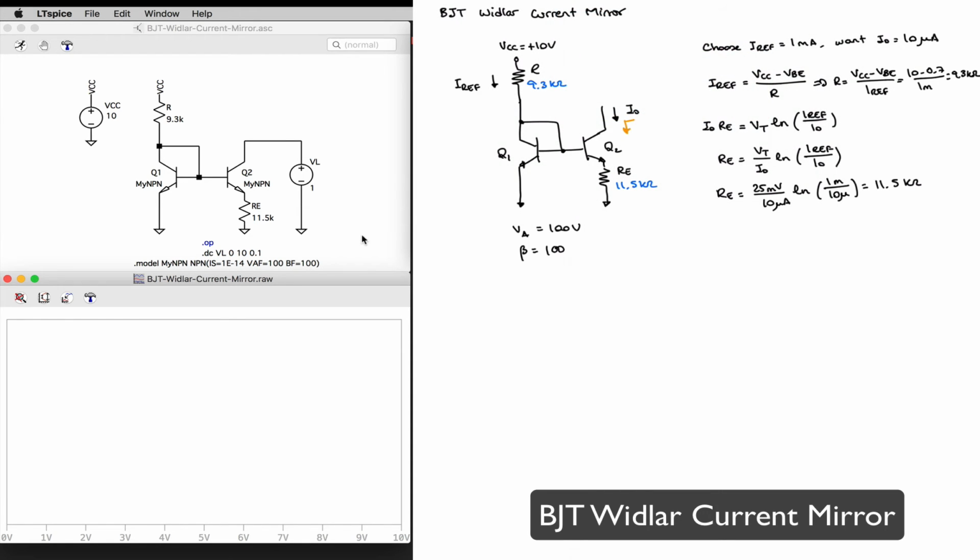And again, I'm expecting my output resistance, in this case, to have the same form as the emitter-degenerated current source. So little r2 times 1 plus gm of transistor 2 times (r pi 2 in parallel with the emitter resistor connected to transistor Q2). I can go ahead and calculate those numbers.